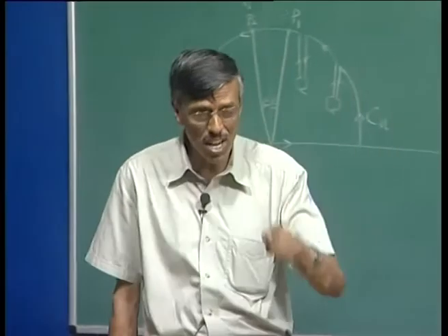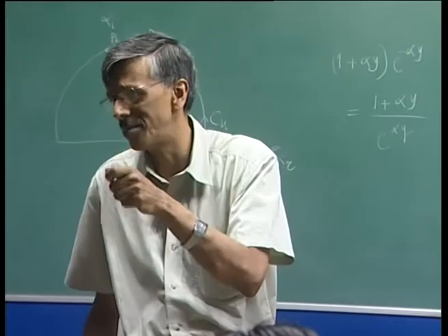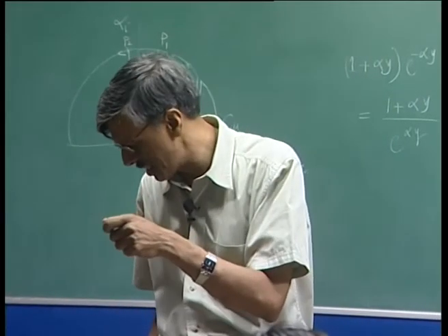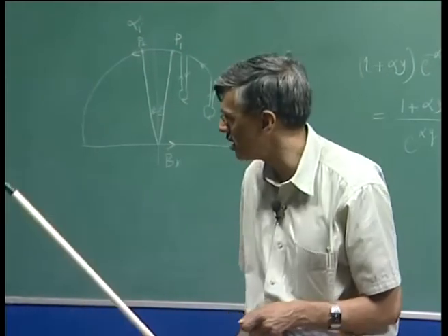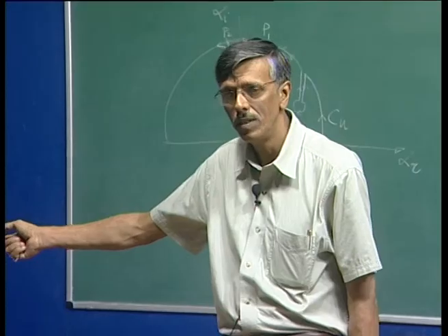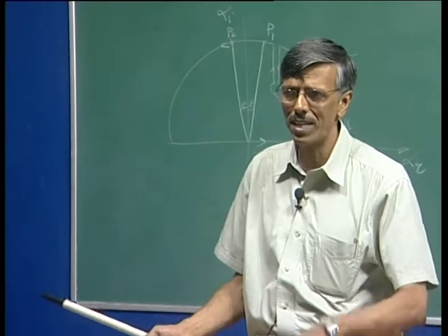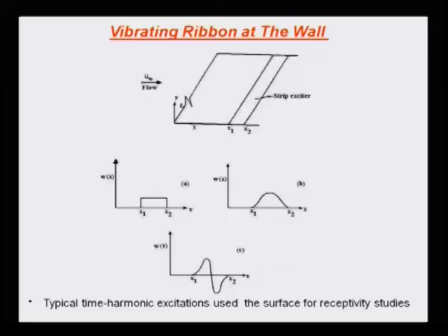But at each and every instant you are going to ensure there is no net mass added. In fact, you would see that in the literature there are lots and lots of articles. People talk about zero net mass jets. You know, this is one way of people trying to control the flow, and you want to control a flow like this. You don't want to create a spurious mass generation or create a spurious sink.